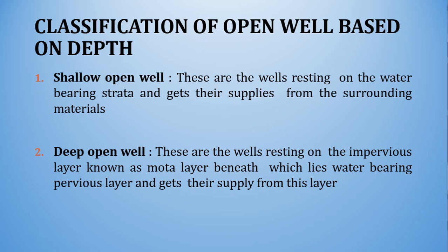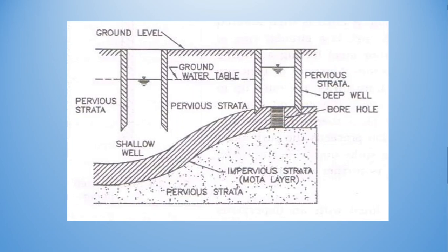And in case of deep open wells, these are the wells resting on the impervious layer known as mota layer, beneath which lies the water bearing pervious layer, and they get their supply from this layer. So we shall understand this particular phenomenon with the help of this sketch.